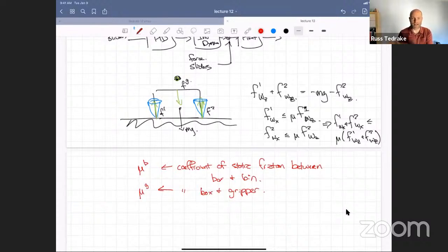We say in my SDF file, I've got a coefficient of friction for this object, and I've got an SDF file with a coefficient for this other. And there's always some little black magic behind the scenes saying, I'm going to somehow average between these two coefficients of friction to make a rule that combines the two into one for every pair, just because you don't want to enumerate every pair of possible coefficients of friction in your definition files.